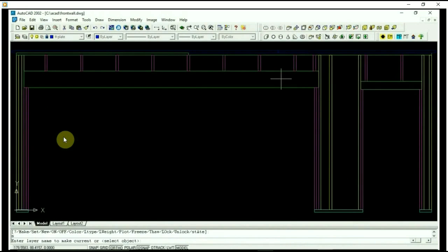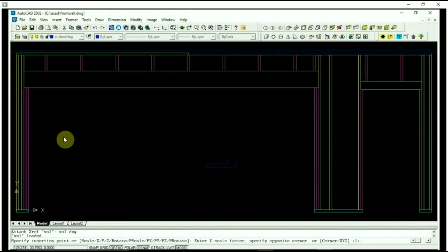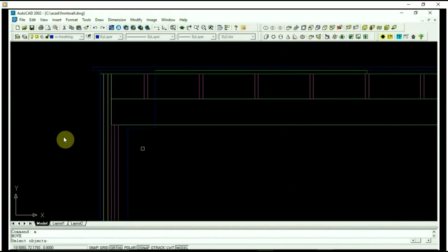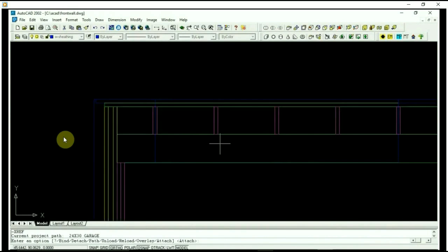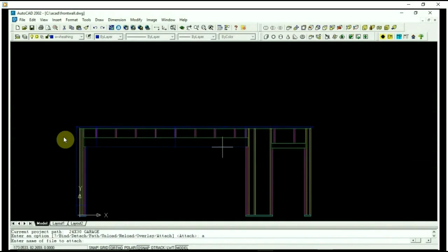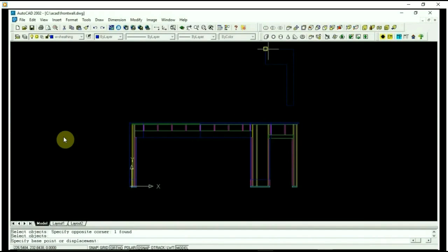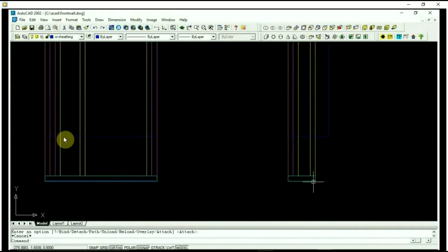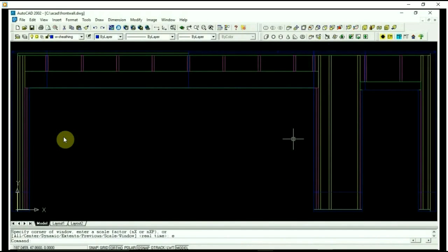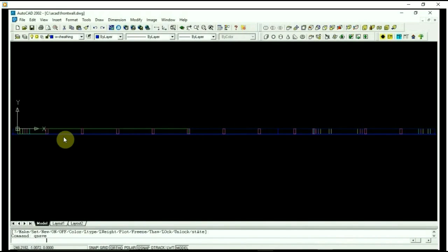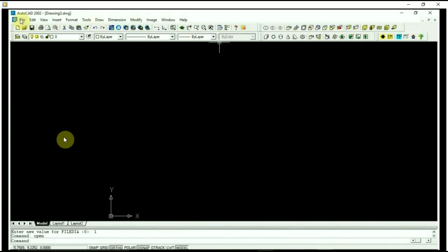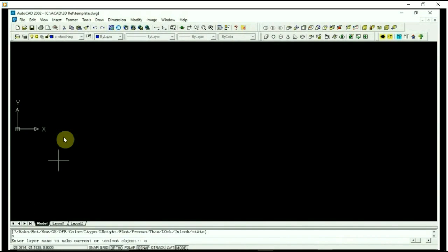I get those placed, and then I rotate it 90 degrees around the x-axis, and then I set the plate elevation in that. So I set it in the one plane, and then I turn it 90 degrees and set the location in the other plane. For the studs and the headers and the sheeting, I do it with the X rotated 90 degrees, so I'm seeing them in profile. I place them in the profile view, and then I rotate it 90 degrees and place them. Like here, the sheeting had to be moved to the other side of the wall, and I place them there and everything lines up.